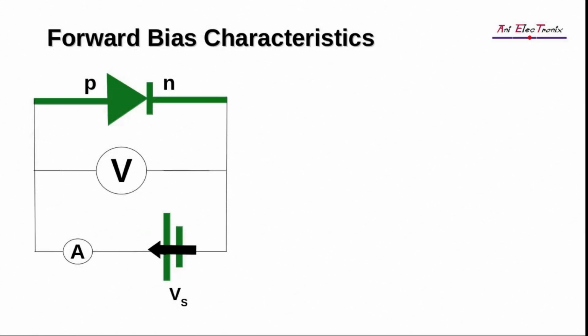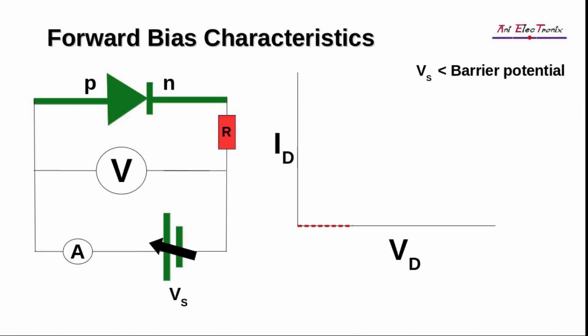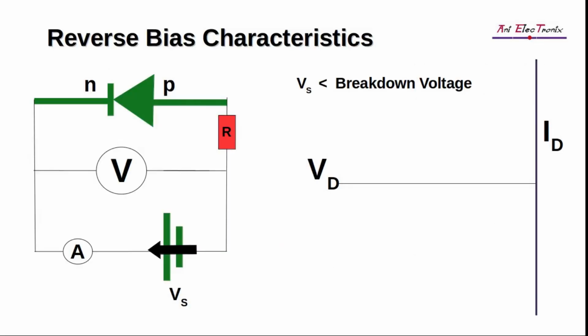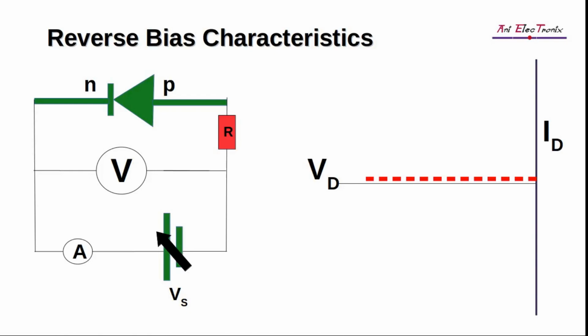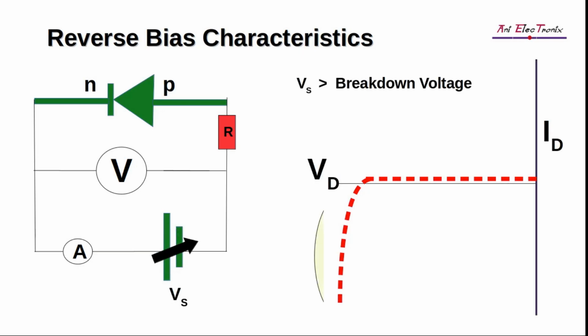It is time for us to review our learning. The PN junction diode's reverse bias characteristics have now been fully understood by us. Could you please suggest anything based on the graph? Pay close attention to the graph stages. Is it not in line with the requirements of a regulator? As the current increases, the voltage nearly stays the same. However, the voltage is not entirely constant. Therefore, it cannot be used as a regulator.